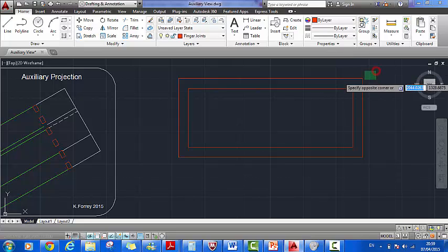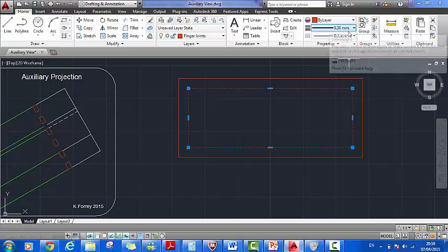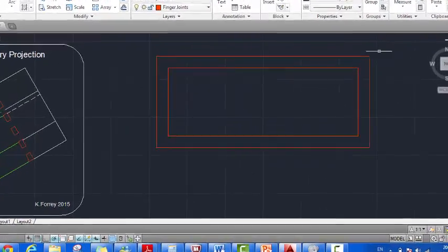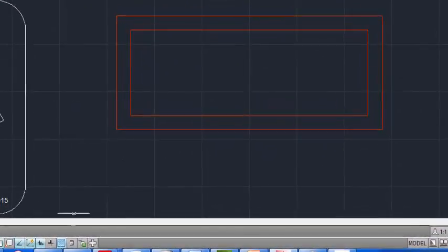Now to double check, just highlight the outside rectangle. This should be 0.00 millimeters. Yes, it is. The inner rectangle should be a thickness of 0.3 millimeters. Yes, it is. Okay, and just one way to check that, if we go down here to hide or show our line weight, we can see here that that's the 0.3.